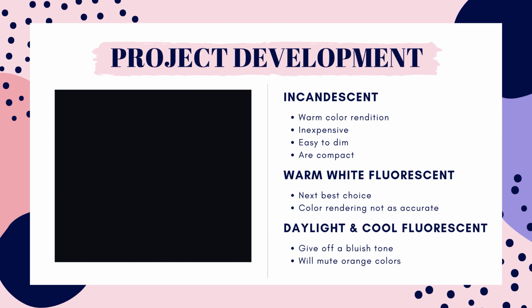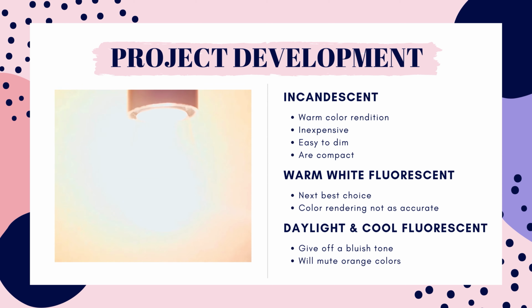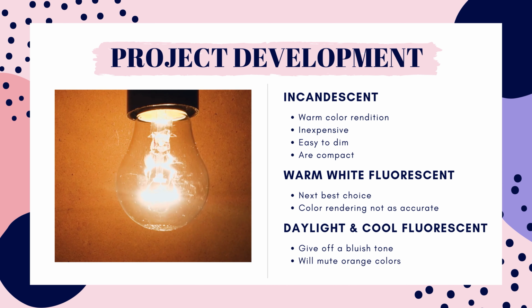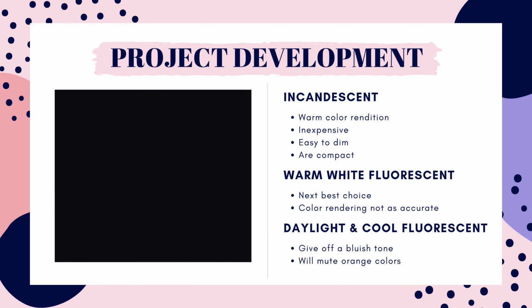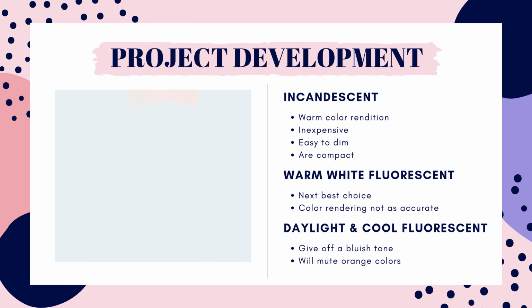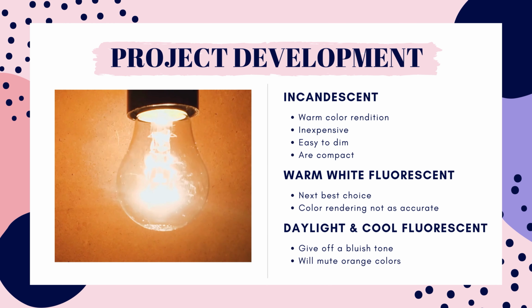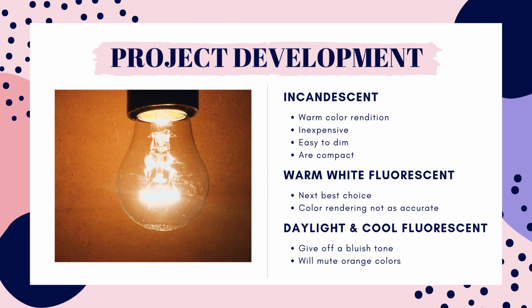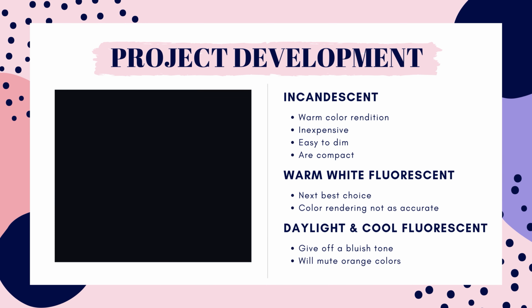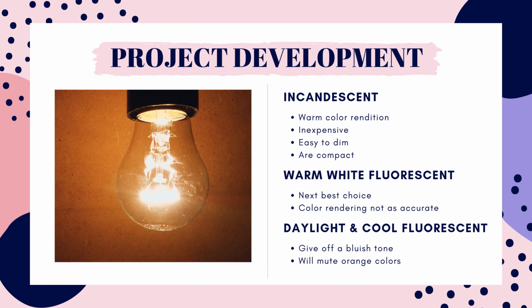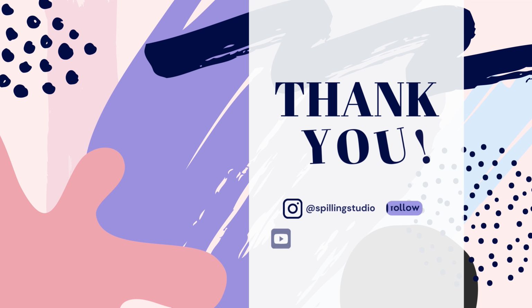And our incorrect answers, warm white fluorescent lamps, would have been the next best choice, but their color rendering is not quite as accurate. However, the owner might prefer this lamp over the incandescent lamps when considering other factors. Daylight and cool fluorescent lights give off a bluish tone and would make the orange look grayer instead of enhancing the color. That wraps up our questions for this week.